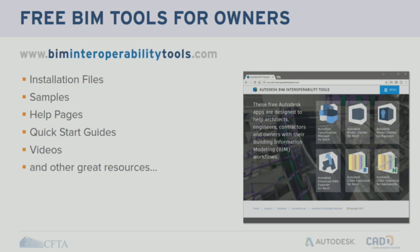Otherwise, one thing I do want to mention, as this has come up in a couple of private conversations. The tools support the same versions of Revit that Autodesk supports: the current release and 3 releases back. So right now we're supporting 2015, 2016, 2017, 2018, and 2019. But the big thing is that the configuration files are consistent from version to version. So if you have a model check configuration in your Ohio State, someone can be doing a model for you in 2016 and using your configuration. Somebody can be doing a model for you in 2018 using the same configuration. So the configuration files are not version dependent. That gives you a lot of flexibility in working with your AE community. They're XML files, right? The model checker's XML, and the classification manager's XLS, the Microsoft spreadsheet.